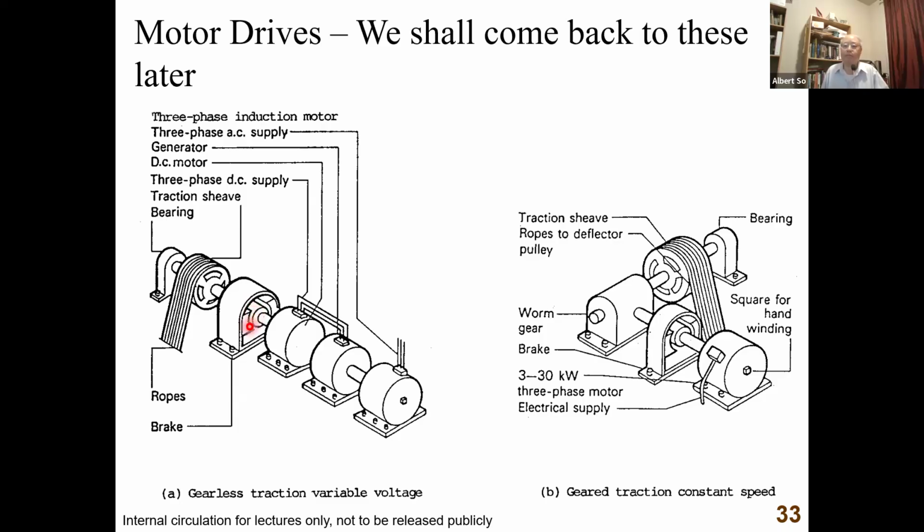Okay, by springs. So when the motor wants to drive the lift car up or down, then you pass a current through the brake, then the brake is released, and the motor will start to rotate. Remember, the torque produced by the motor is the unbalance between the counterweight and the car. Okay, not the full weight of the car, just the unbalanced part.